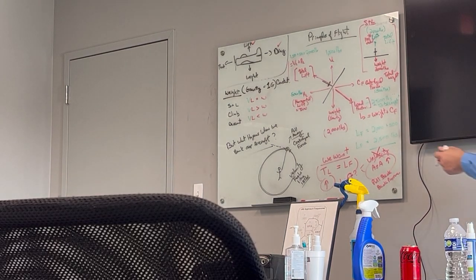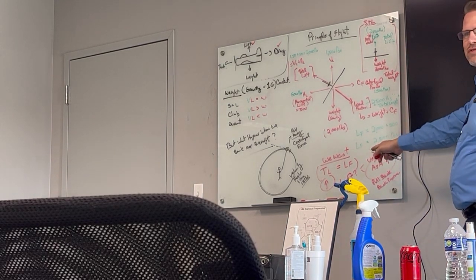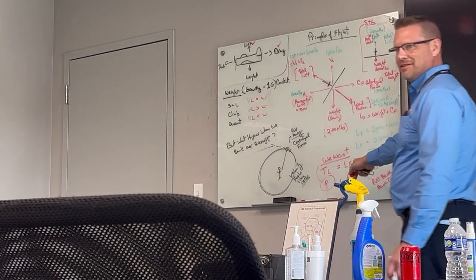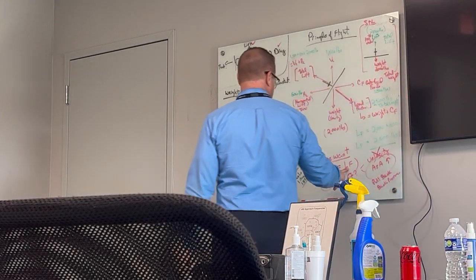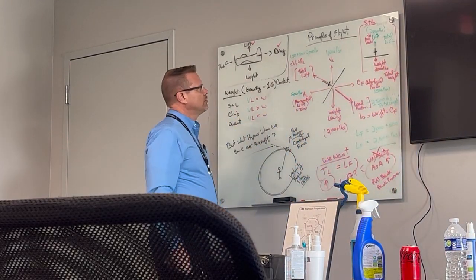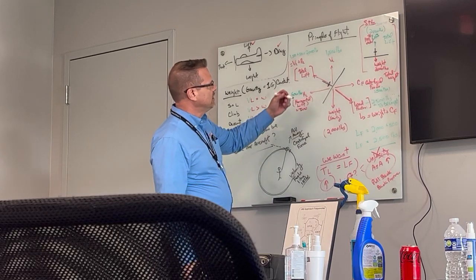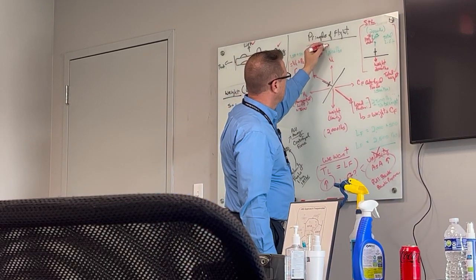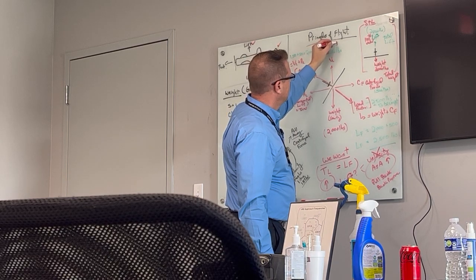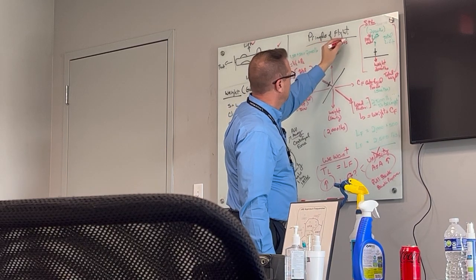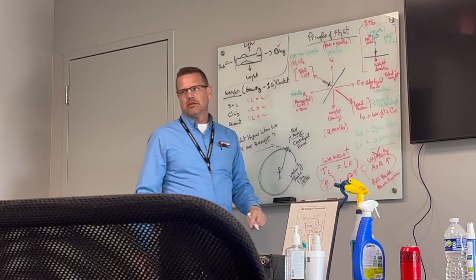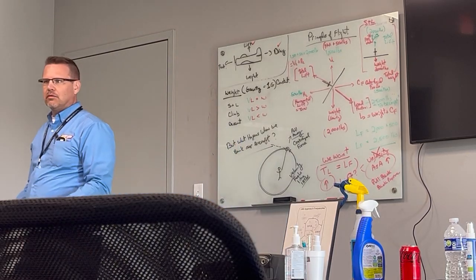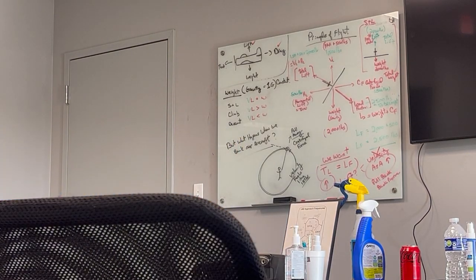Well, how much? Well, enough so that the lift increases enough to equal our load factor now. So how much would we need? We'd need to pull back. We'd need to increase our angle of attack to add 500 pounds of lift. And if we did that, the equation would balance, and we'll do a normal level turn, right?